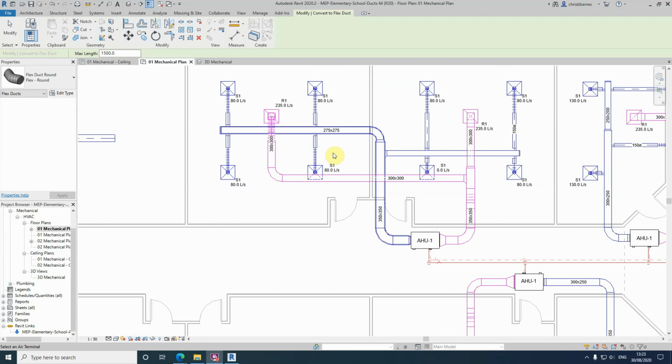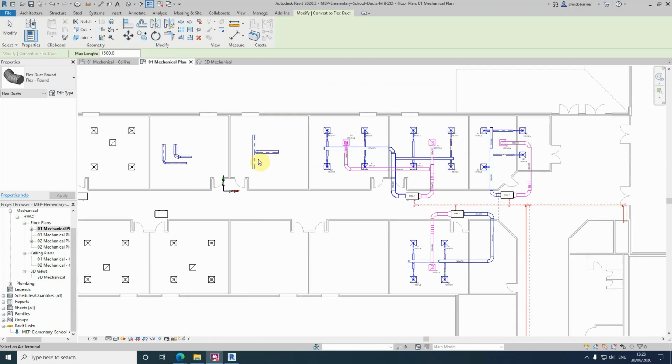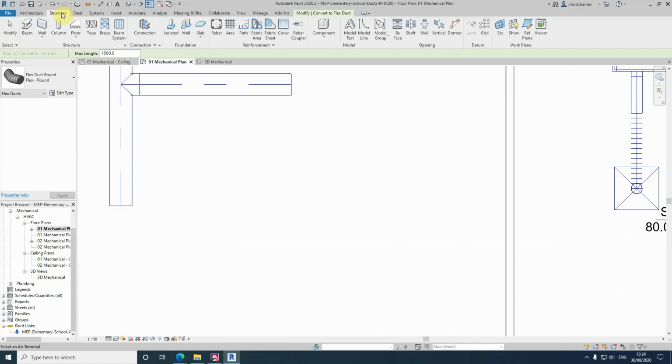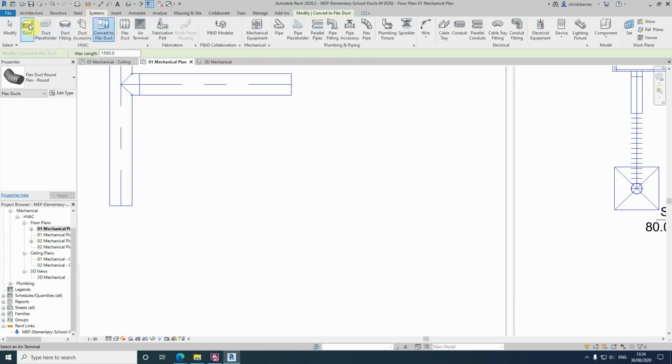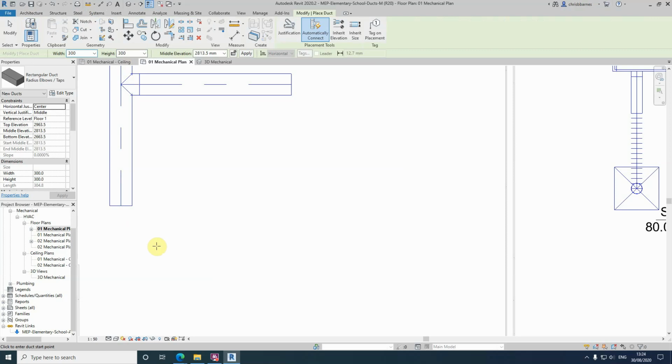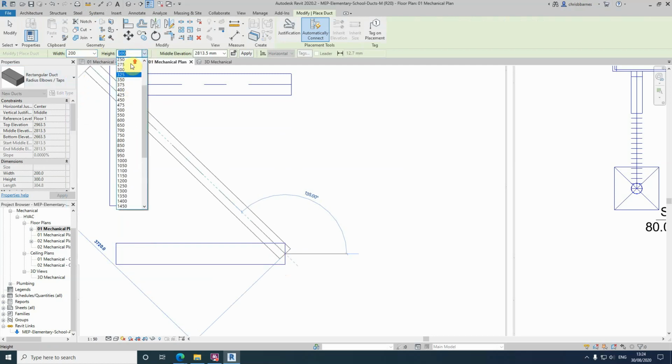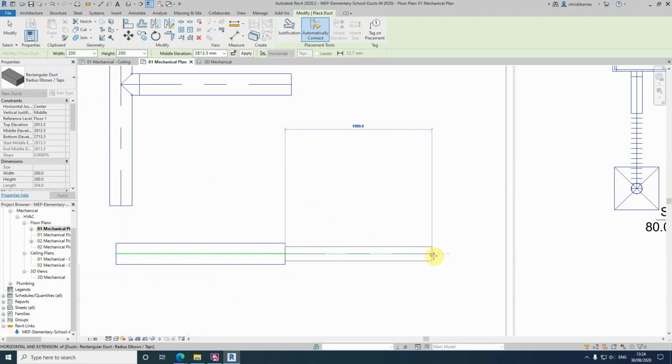Now if your duct run has different size ducts, we can actually amend our justification, so that it can align from the bottom, middle or top, or even to the sides. So if we show this example, duct 300 square to here, and then we go to, I don't know, 200 by 200, and then continue on.